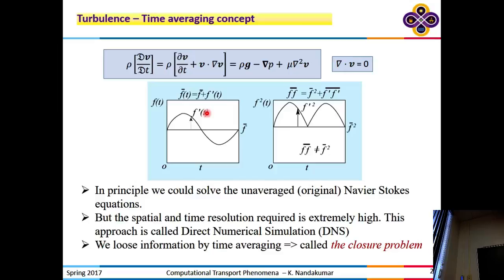Because I have a quadratic term here. So when I take the integral of this, I will get a mean term. The perturbation term would drop out. When I take an integral of this, same thing happens. When I take the integral of that, same thing happens. Because I need to take the integral of that, but you can switch the order of differentiation and integration if the function is continuous, etc. So all of these terms will behave and give you the equation in terms of the mean field, except this equation. When I plug it into this equation, I'm going to have a quadratic nonlinearity.